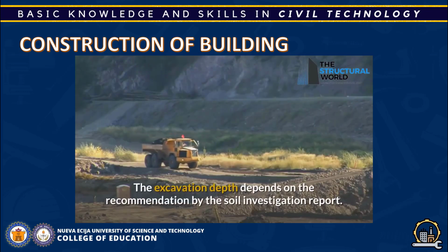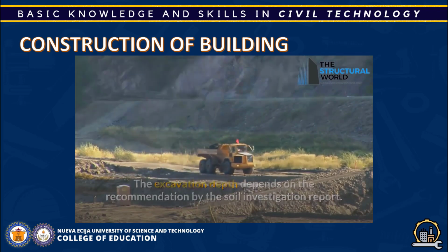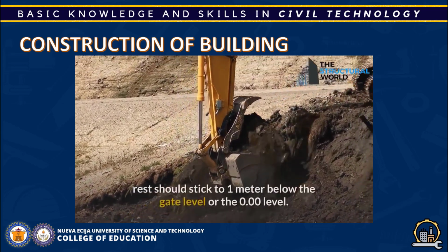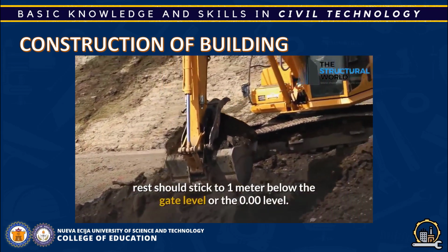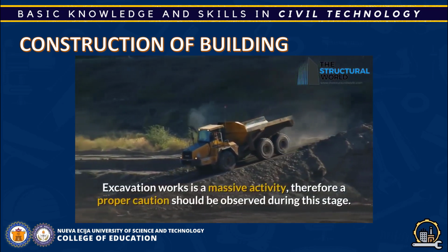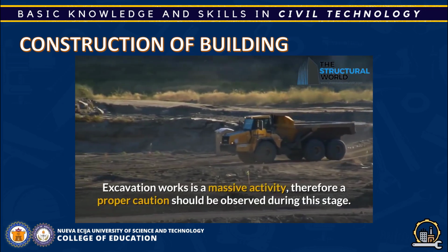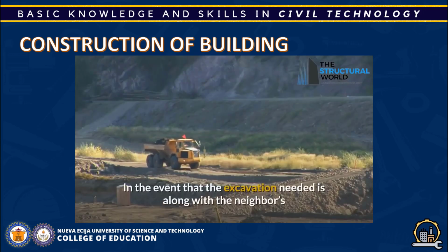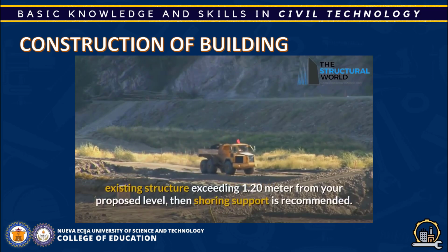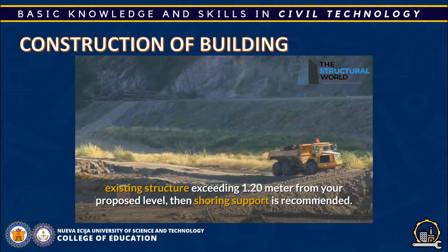The excavation depth depends on the recommendation by the Soil Investigation Report. But it is safe to say that the minimum excavation level for the footing to rest should stick to 1 meter below the gate level or the 0.00 level. Excavation works is a massive activity, therefore proper caution should be observed during this stage. In the event that the excavation needed is along with the neighbor's existing structure exceeding 1.20 meter from your proposed level, then shoring support is recommended.